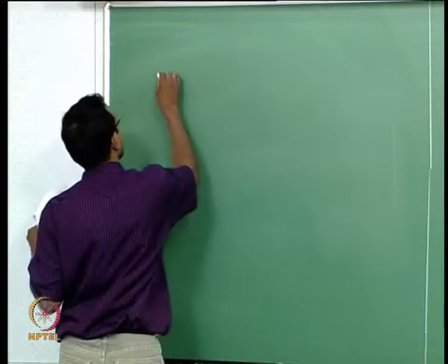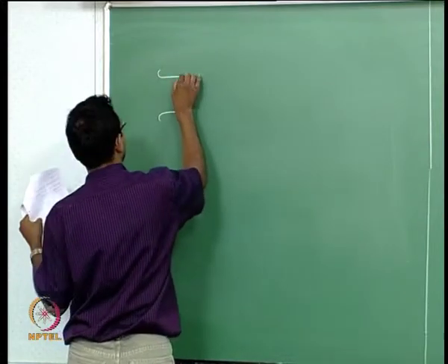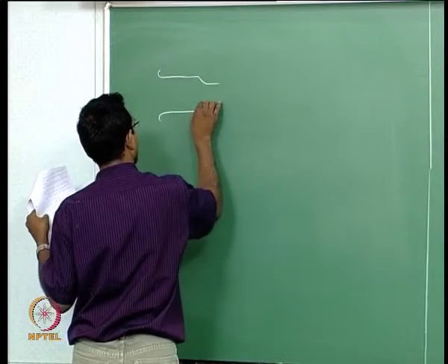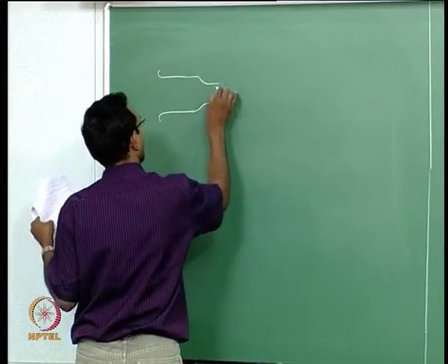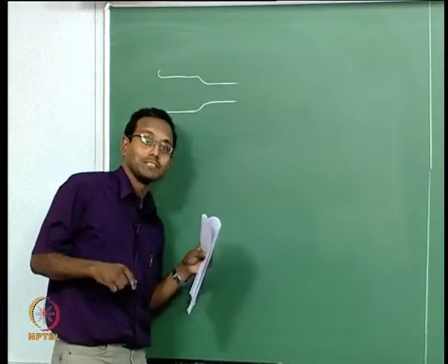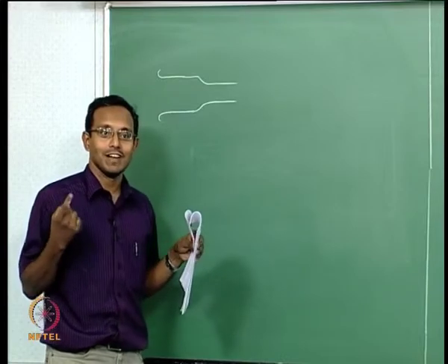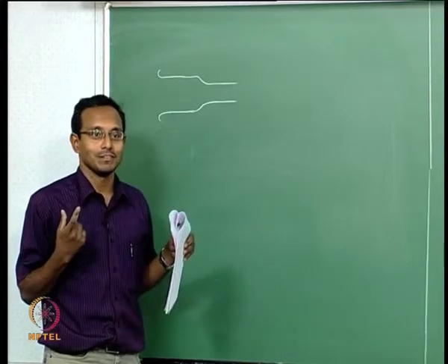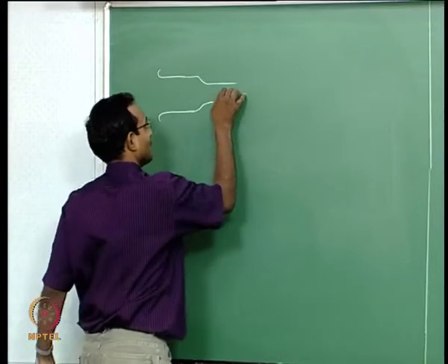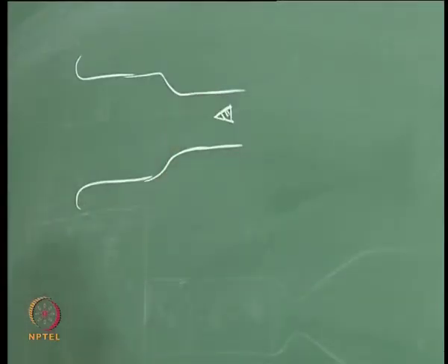redraw the whole thing. The tunnel looks somewhat like an in-draft tunnel. I am just drawing one of the facilities possible, and in this case what I am thinking about is it is transonic, which means my model should be sitting at the throat of a nozzle, right, because at the throat of the nozzle only you get M equal to 1. So I have to put a model at the throat of the nozzle. Okay. And now you know why I talked about that other thing.